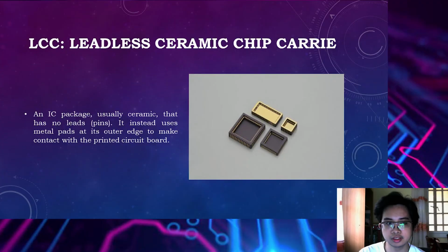Another type of packaging is the LCC, or the leadless ceramic chip carrier. It is an IC package, usually ceramic, that has no leads or pins. It instead uses metal pads at its outer edge to make contact with the printed circuit board. This makes the device easier to fit to the PCB.